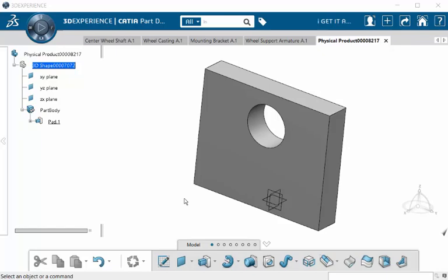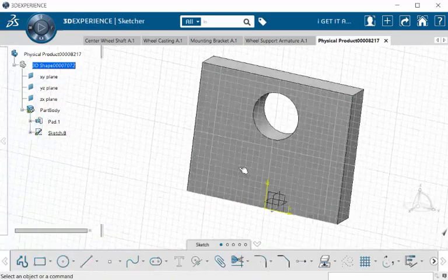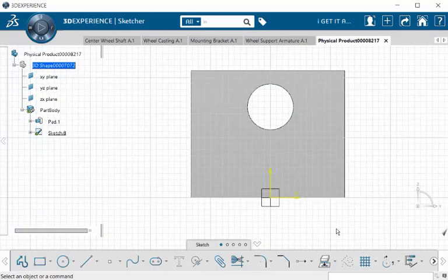I want to use lines from the solid part to create pads from. And what I mean by that is I'm going to first select a position sketch, and I'm going to select the face right here. Now, Project 3D Elements is only located within Sketch. So that's located actually right down here.